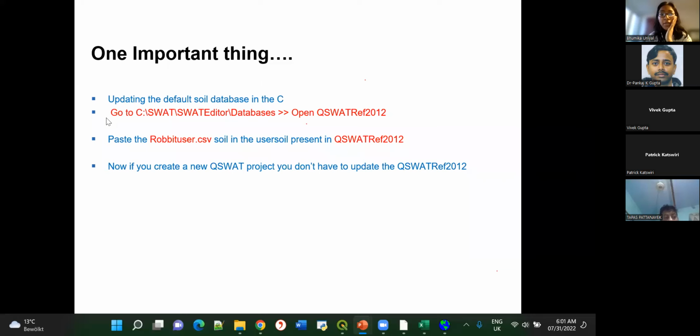I have already provided you the information. You could go to this database, which is present in the folder where you have created the model. But if you don't want to do it every time, you could directly go to SWAT, go to SWAT Editor, click on databases, and there you would also find this QSWAT reference 2012 database, and you could also copy your user soil there.